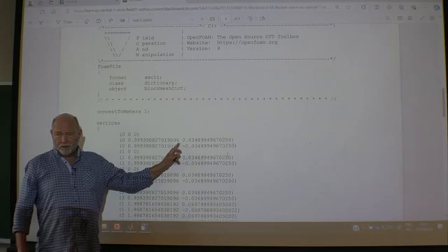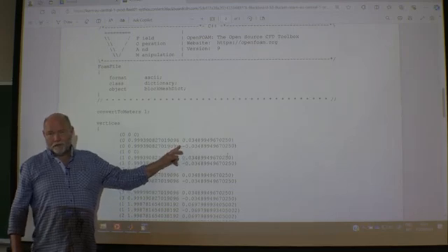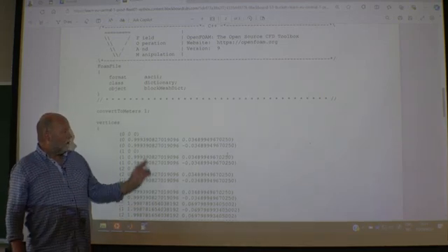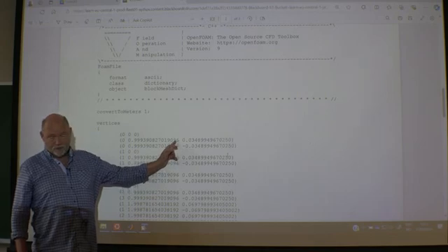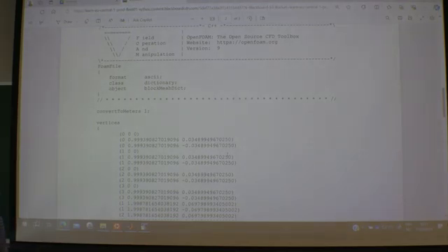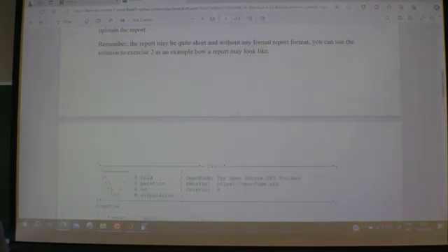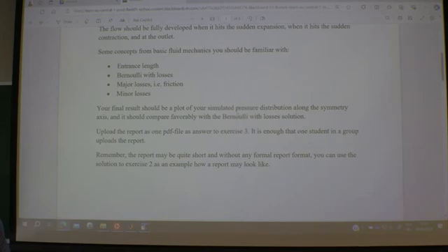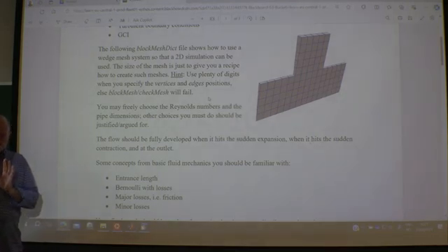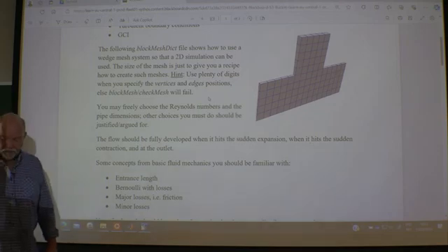I just used format long in MATLAB, calculated the positions, and cut and pasted. This is overkill, I guess, but use at least 18 digits, or else blockMesh or checkMesh won't accept the mesh. It's going to crash. So you have to be quite accurate when specifying the different positions.